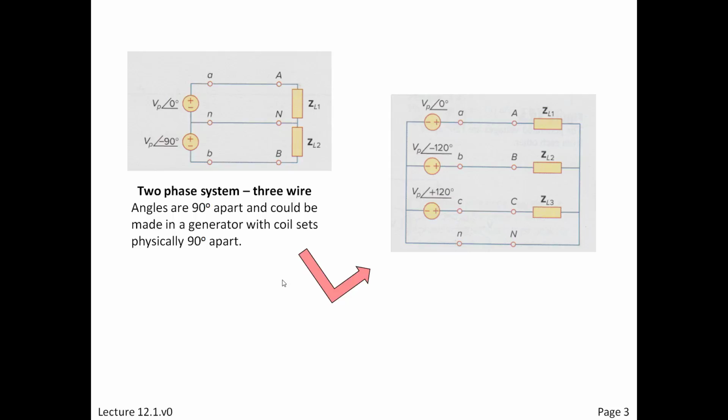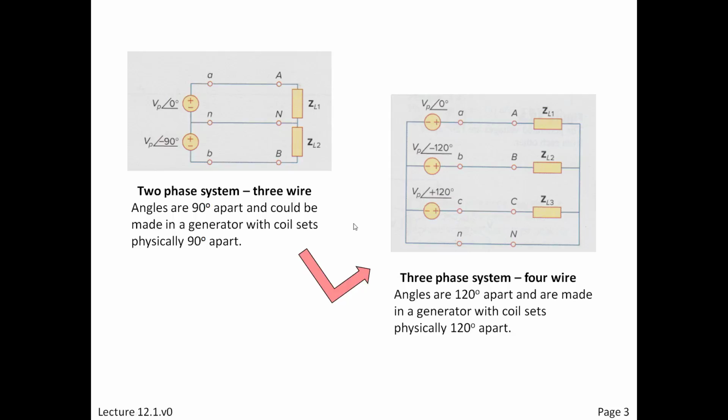So the usual technique in discussing this, as you move from a two-phase three-wire system, is that we want to get to three-phase, and we begin with it as a four-wire system. The straightforward connection, or the analogy from the two-wire system, is we just add another source and a load down here and share the neutral.